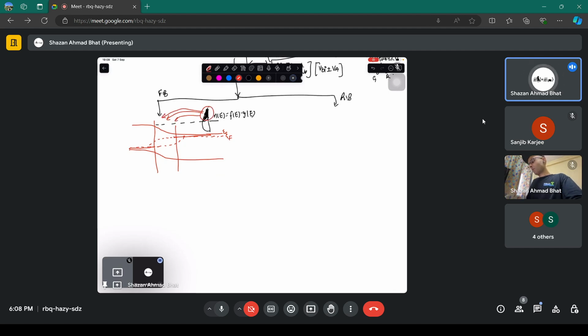That's why most of the current flows because of the diffusion in case of the diode. And similarly, you have the hole distribution. Those holes which have energy about this, they are able to diffuse to the other side, and you have a conduction because you have applied positive on this side, negative on this side, because this is a forward biased case.